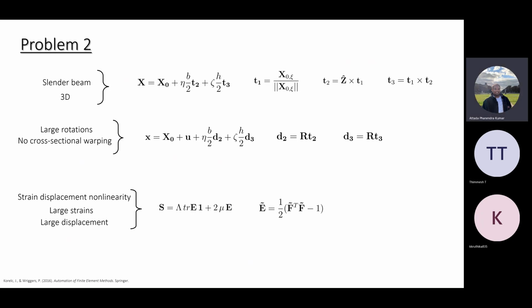So now, based on the strain displacement nonlinearity and isotropic assumption, we have a 3D constitutive law of the same isotropic that I showed you in 1D, sigma is equal to E into epsilon xx. We'll have a 3D constitutive law here. But since we are considering large strains and large displacement, we have to consider the Green-Lagrange strain tensor and second Piola-Kirchhoff stress tensor instead of our Cauchy stress and symmetric strain tensor or small strain tensor. So this is the strain energy.